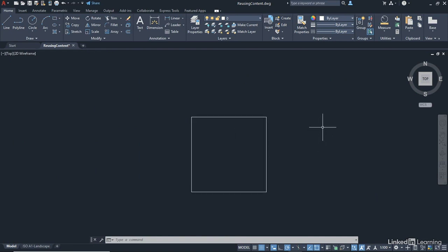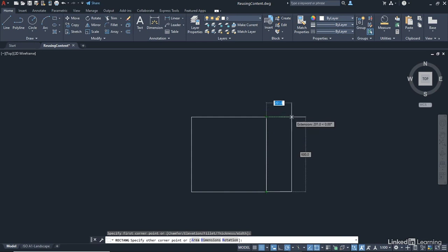And we're going to create some really simple rectangles off of this and use the mirror command and just make it look like a sort of lounge type chair that you might have in an entrance area of a building. So back to the rectangle command, and I'm going to click here like so. Click that point there, and I'm going to come out, but I'm going to hover over this endpoint here and drag outwards like that. And I'm going to type in there 150.